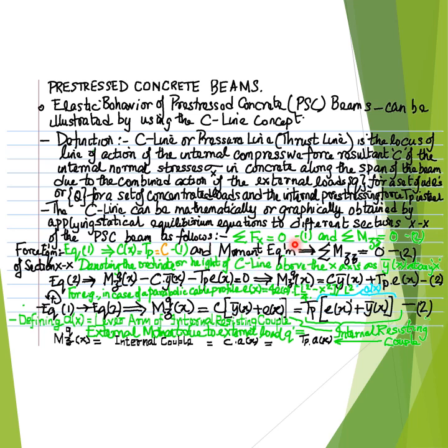Additionally, the moment equilibrium equation, that is the statical equilibrium equation that represents the statical equilibrium among the bending moments about the z-axis, imply that the summation of all the bending moments sigma mzz due to the various force resultants of the internal stresses in the concrete and the pre-stressing force in the pre-stressing steel about the z-axis should equal 0.